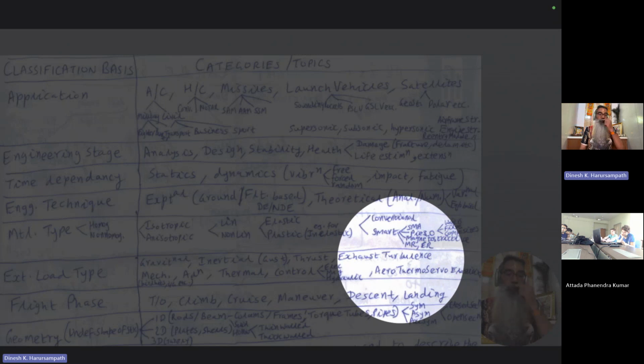The next thing, in terms of some more secondary kinds of loads, is the turbulence that is there not only from the air, but the turbulence from the exhaust from the engines. So especially jet engines, when you have the velocity at which the exit takes place, because that's what creates the thrust for you, is so large, and the temperatures are so large, and it's not just air. Remember, it is air which has the burnt fuel in it, and therefore the chemistry of it, the thermochemistry of it, and the overall properties of that exhaust are very, very different.